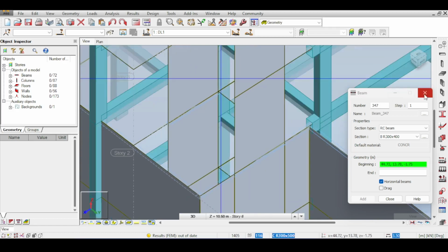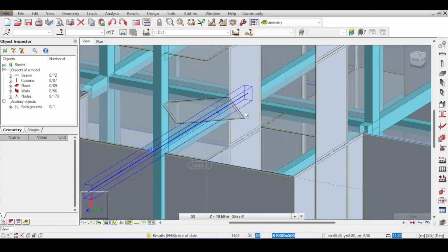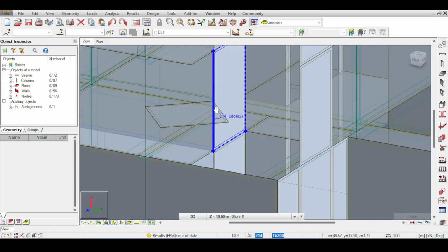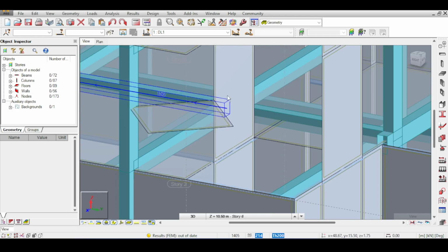Look and follow me. I'm thinking of this. This represents the mid-height, right? This is where the first flight of stairs, and then landing and second flight of stairs. So I'm thinking how I'm going to carry that. Now, I could have a beam that cantilevers out of the wall, but I'm thinking about the connection issues here, because I would have to cast the wall mid-height and even quarter height, I guess, because I want to have a rigid joint. This is a fixed support here.